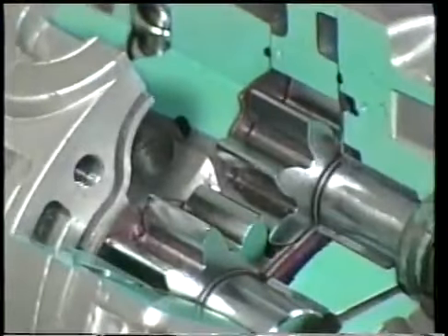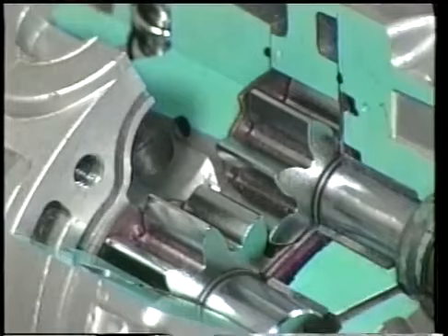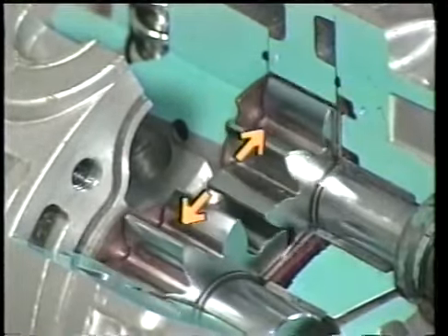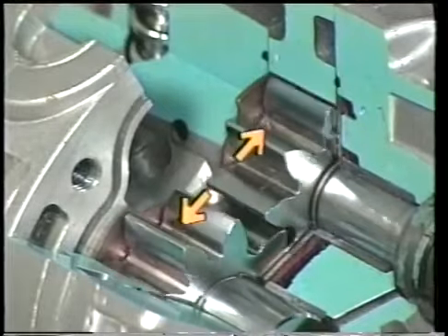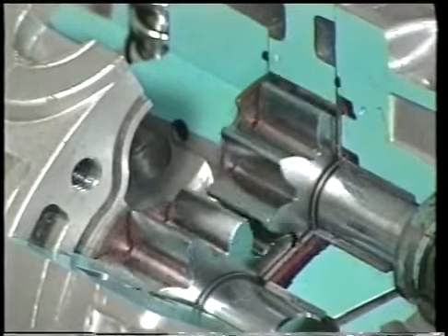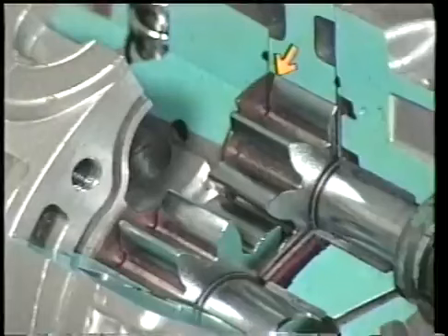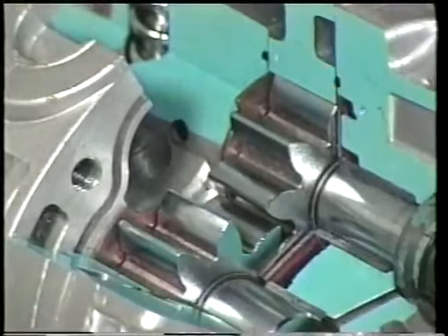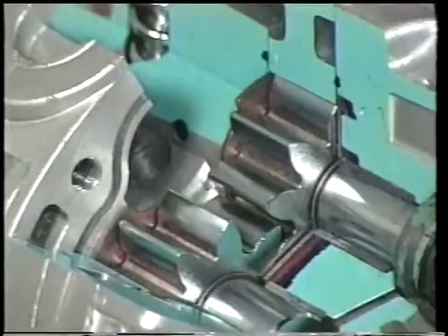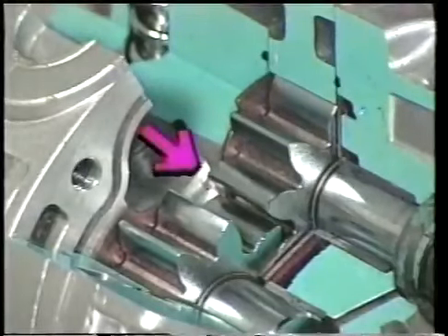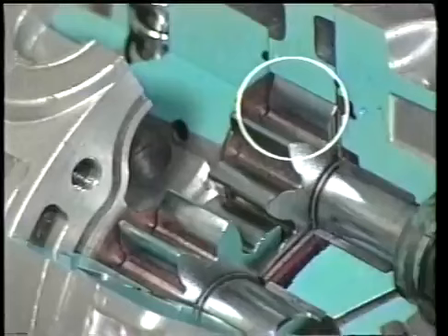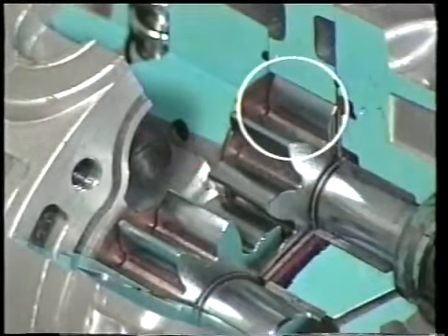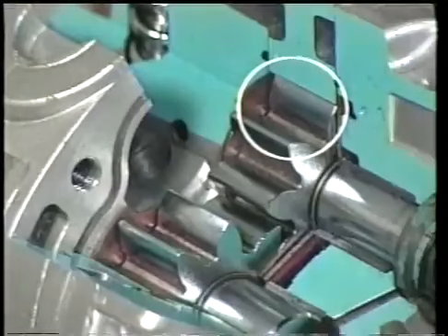Gear-type hydraulic motors operate in a way that is similar to vane-type motors, except pressure at the motor inlet pushes against the sides of the gear teeth, forcing them to rotate. A tight seal between the gears and the housing minimizes fluid leakage past the teeth. The torque created at the motor shaft depends on the pressure at the motor inlet and on the exposed tooth area. The greater the pressure, the greater the torque, and the more exposed tooth area, the greater the torque.